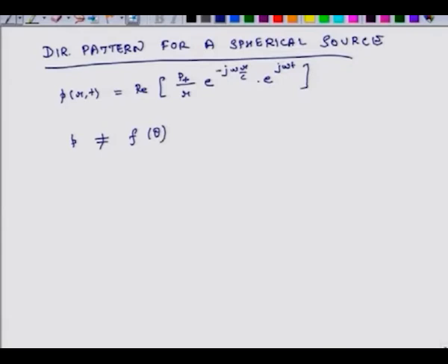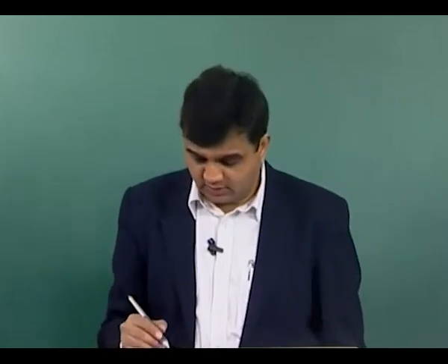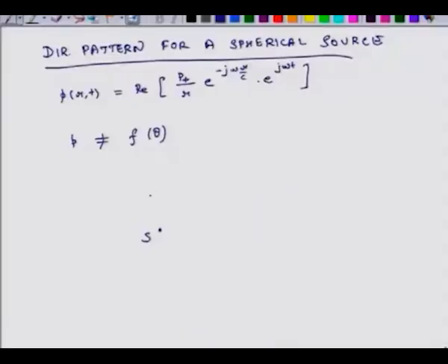What that directly means is that if I have a sound source, let us say it is a point sound source and it is emitting radial sound waves, then the directivity pattern for such a sound source will be circular in nature. So, the sound source is located exactly at the center of the circle, and that is my directivity pattern.